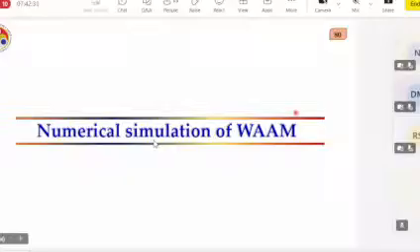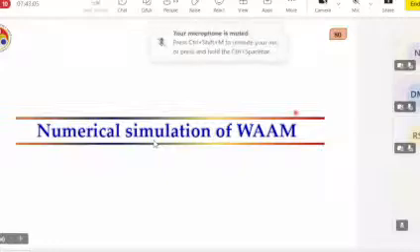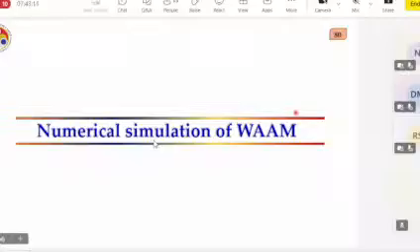developed by Goldak. If you consider the focus of the front ellipse as the origin, with the minor axis as the y-axis and the major axis as the x-axis, then we can get certain parameters of this molten pool, like a, b, and so on. By defining these, we can get the heat at the front and the rear. This is because the heat concentration is quite high at the beginning, as it comes directly from the arc, and when it's moving forward, the rear end of the heat source has somewhat lesser heat energy.